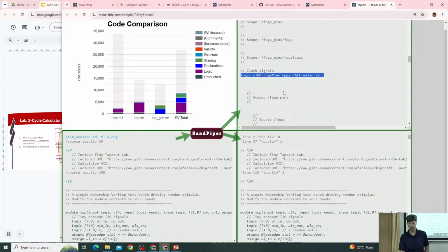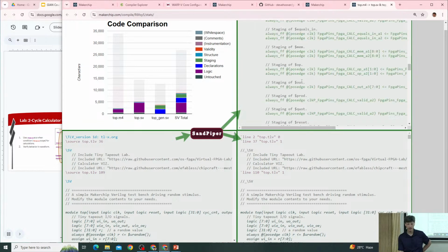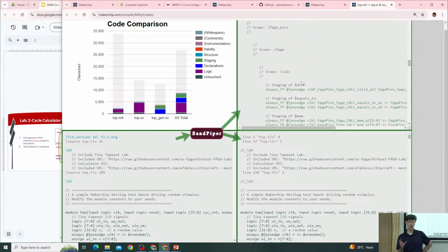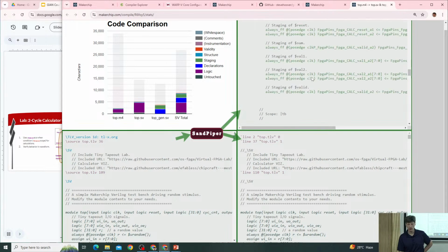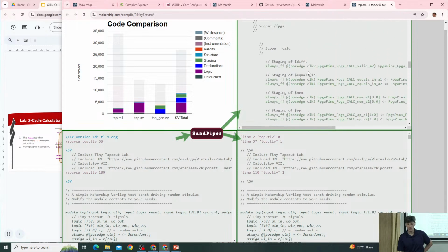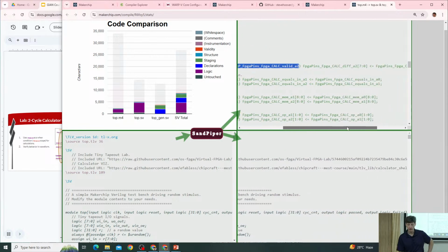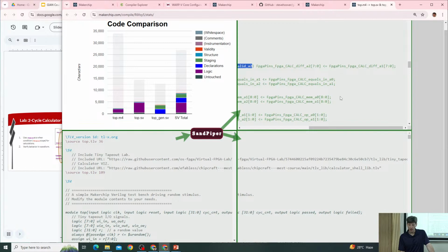So generally here the clock gating. This is one of the clock signals that's conditioned on valid. I guess it's the only one. So the particular code that we gated was all just in one cycle. Does it even get staged? So this is the clock. Let's see where this is applied, actually. So the green is my flip-flops, and some of those flip-flops now are using the gated clock signal. So let's see what this one is. This is the flop of our diff.